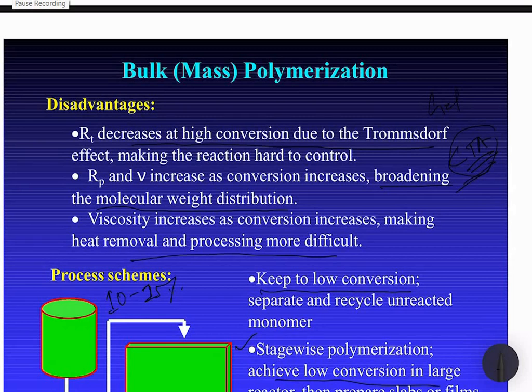So use of a chain transfer agent can further widen the molecular weight distribution, whereby the chain transfer agent stops the polymerizations which have started later and are growing at that point, say after 1.5 hours or 2 hours of the reaction, when we have some 40 to 50% conversion. At that stage, whatever growing chains are there, the chain transfer agent actually terminates them.